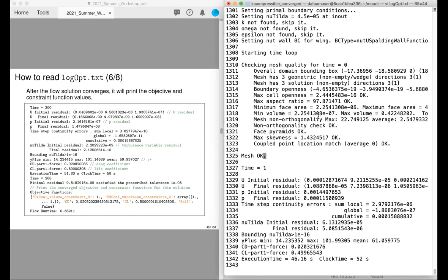Okay, so it's operating with the same checkMesh options that I have in general OpenFOAM. That's right. It's the same, but we can relax the tolerance. Say, for example, if skewness is 4.5, we can still return mesh okay. So this can be set up in the run script. Okay, good. So actually, this will be used quite often if you use snappyHexMesh. All right, very good questions. Thank you. Let's move on.